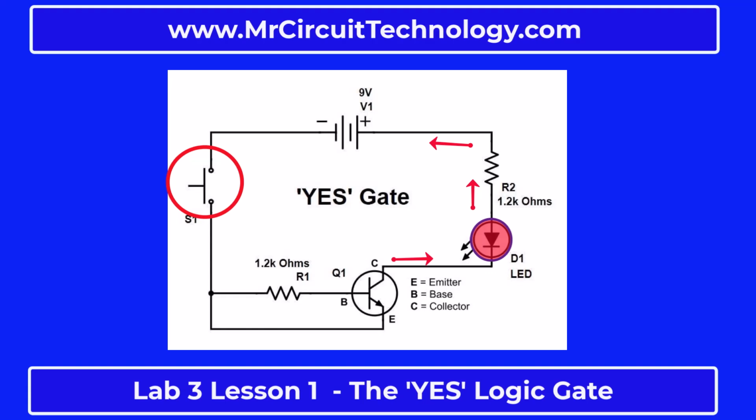When you release switch S1, you remove the voltages from the transistor and the LED turns off, indicating a low on the output. So, as you can see from this explanation, this circuit works like a yes digital logic gate. When the input is true, the output is true.